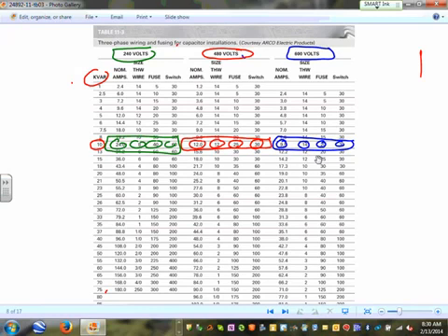Any comments? Any questions? So, Derek, I'm going to do a calculation, guys, for the 10 kVAR, and I want you to do the calc based on the code. If you come over here and find the different values, please use the ones I'm going to do. But typically, these are standard industry. The calculations have been done for you. So what they did, Karen, here is to size the wire, typically these three, they use 135% of the full load current.